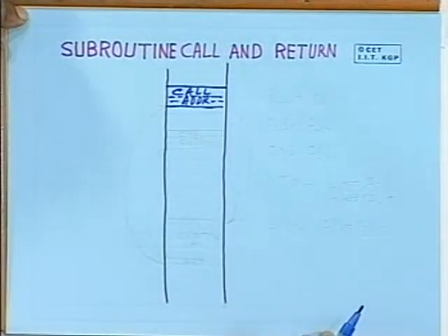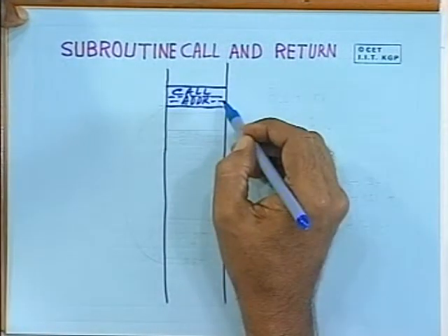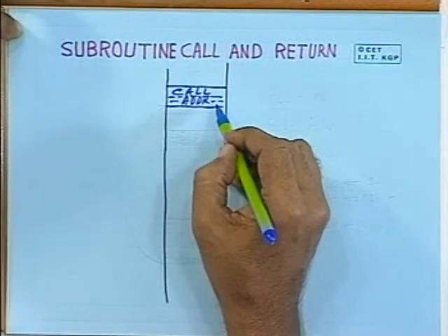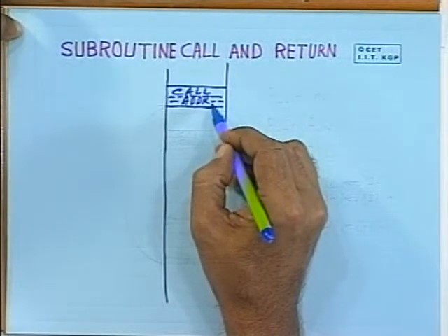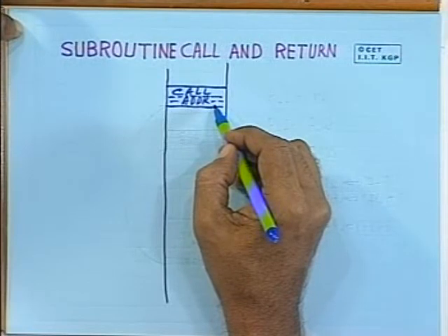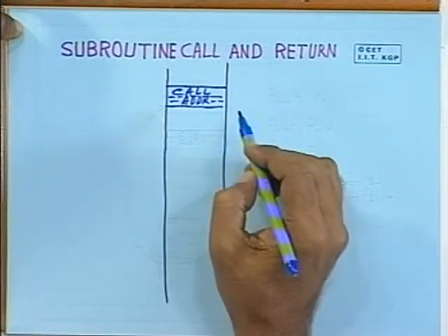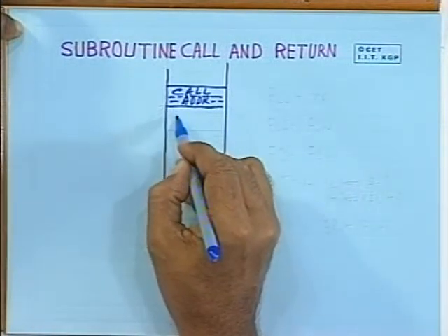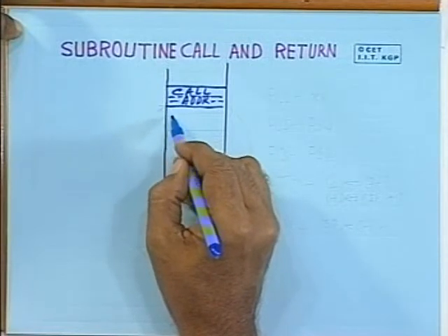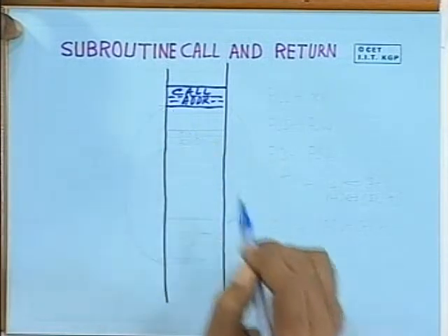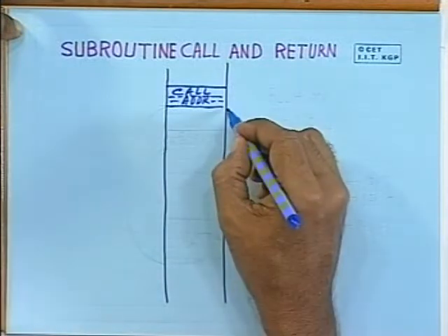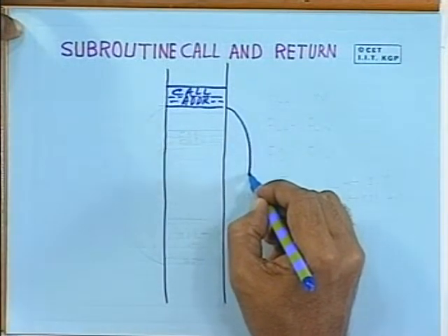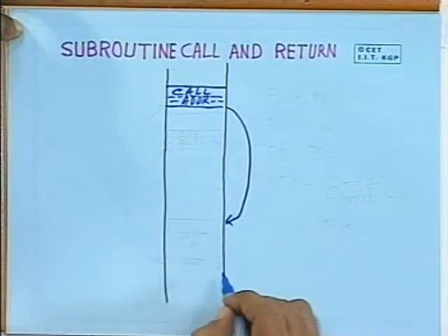What will happen because of this? First, as we have discussed, this address will be loaded into the program counter, and the next address, this address which is immediately following this instruction, will be loaded into the stack. So the jump will take place to the beginning of the subroutine.